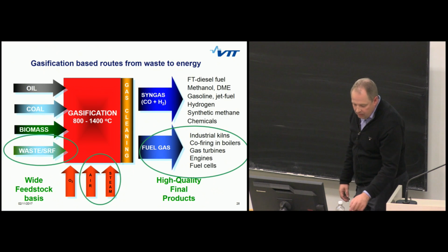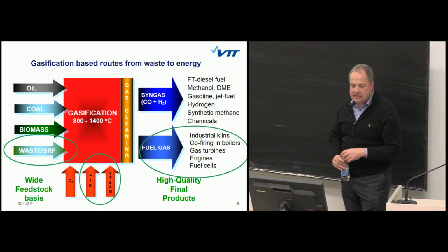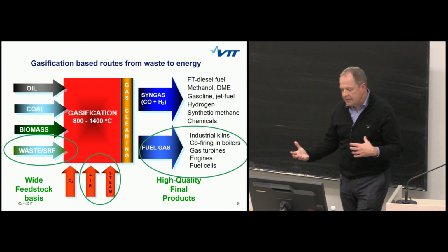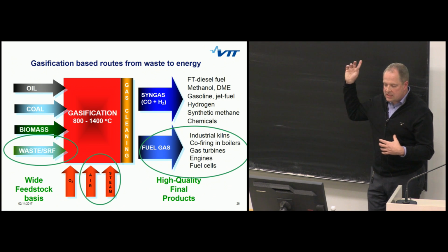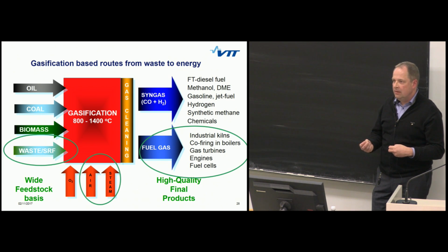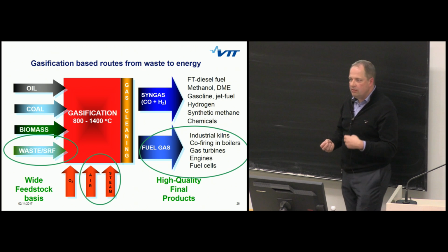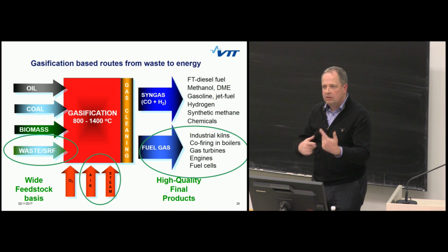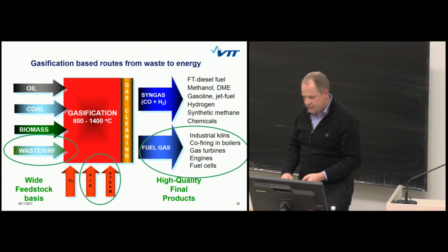And of course, what we are working on at VTT is the gasification-based routes, and really looking at gasification of waste and looking at also the way of using the fuel gas, of course, as a fuel, but also looking at what we can get out from the ash. Because the minerals, for example, if you combust something or gasify something, you will have ash of the non-combustibles. And then how you reclaim minerals and metals out of that ash.